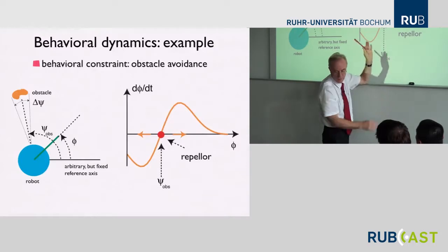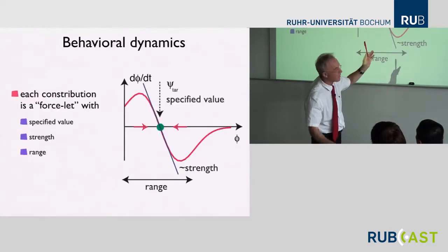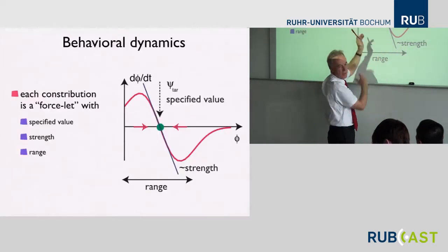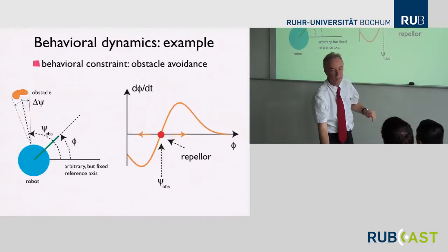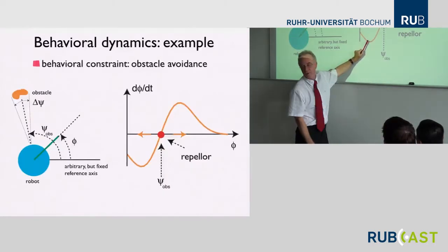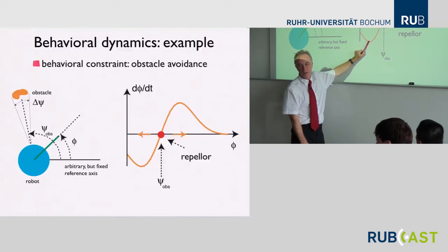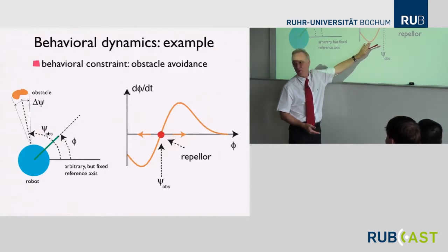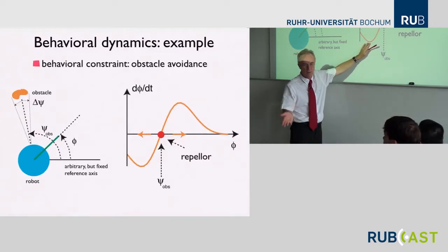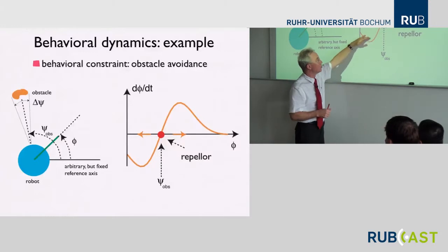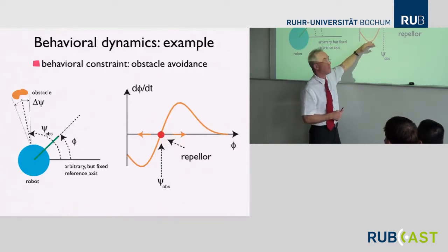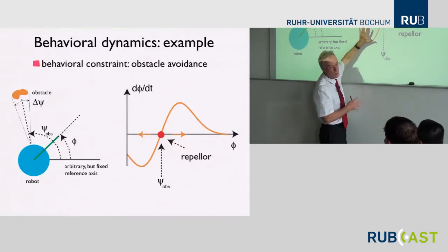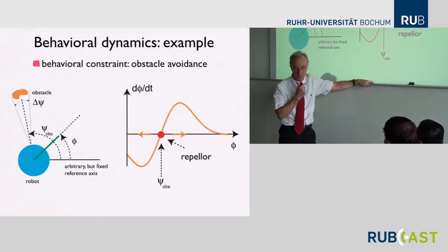I'll say that in a moment, I think I have a slide like that. We limit the range, and as a trade-off, this highest rate of change emerges. And in robotics, in actual implementations, you have to design that because your maximum acceleration will be limited by control stuff, and you make sure that the function isn't hitting that, so you make sure that you rescale everything to be correct.